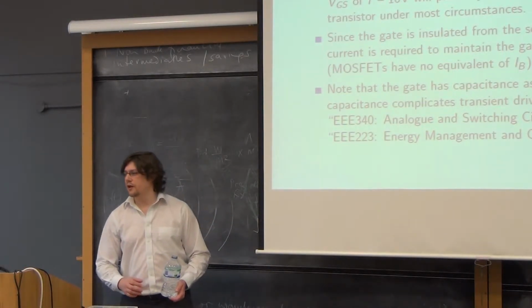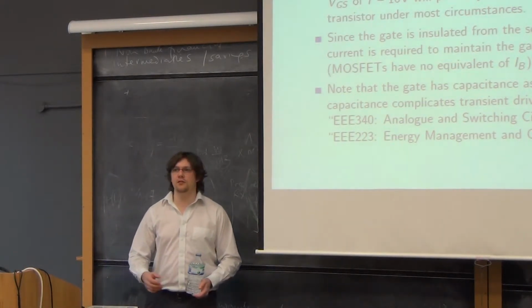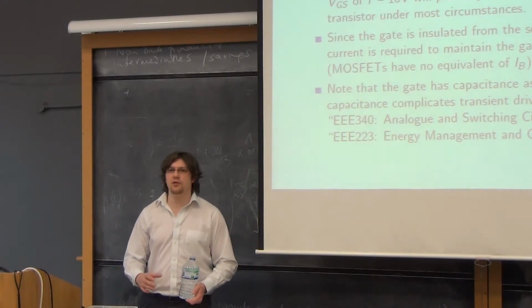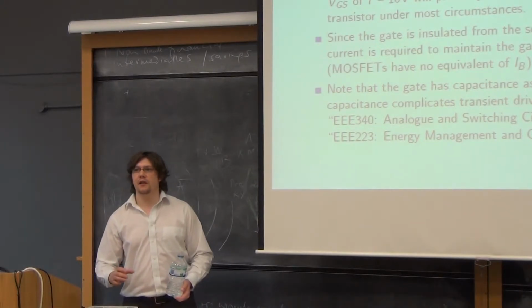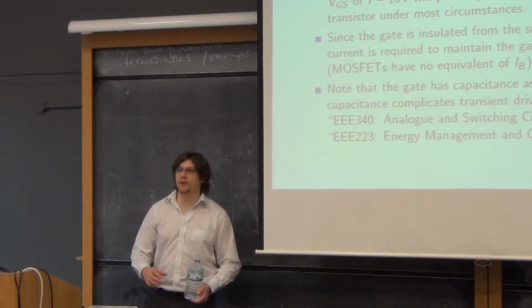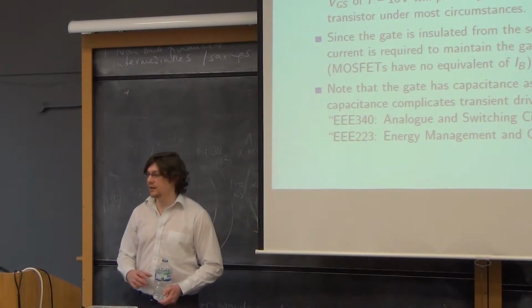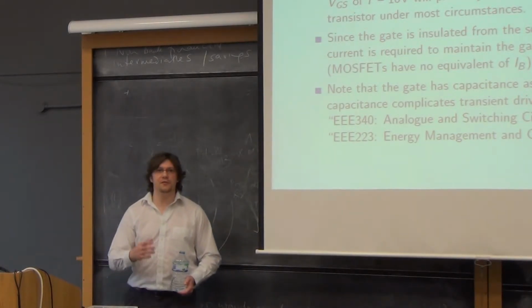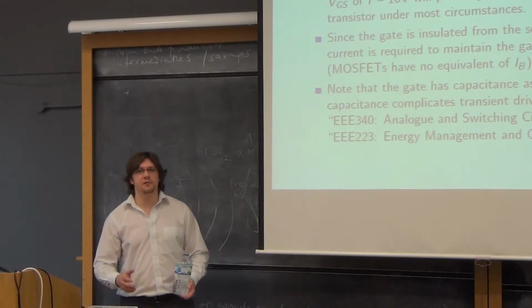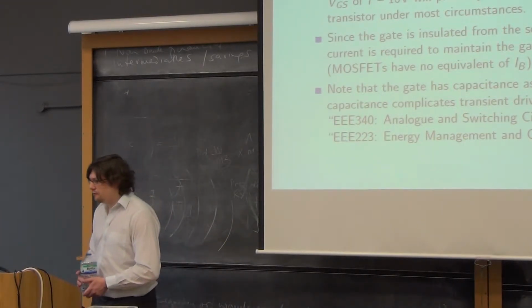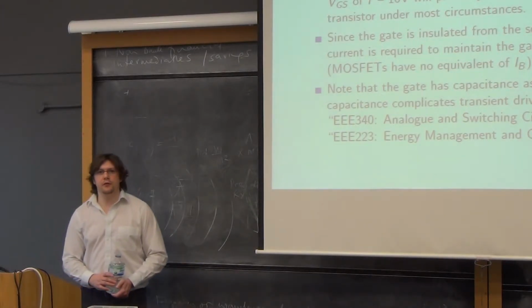It doesn't work for me, because you can't apply that to a MOSFET because there is no IG to control ID. We have to talk about VGS and ID, and for that reason I'd like to talk about bipolar transistors as having VBE and IC as well, because then we have one unified situation for all three terminal switching devices. You'll find most textbooks will be doing it the way I'm doing it as well.